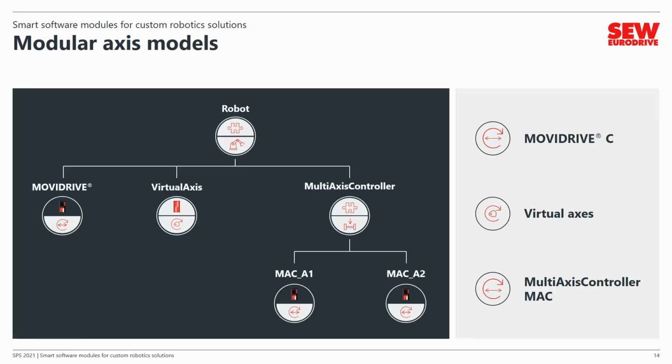Application examples include hoists and overhead gantries, for which a drive at each side provides motion in the same direction. The motion of another 2 drives or even groups of 2 drives each at either side can be controlled in further cascades.